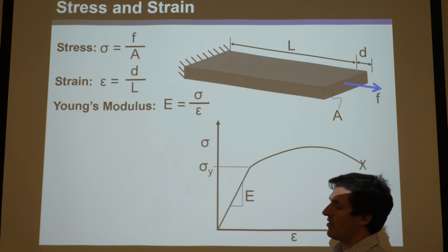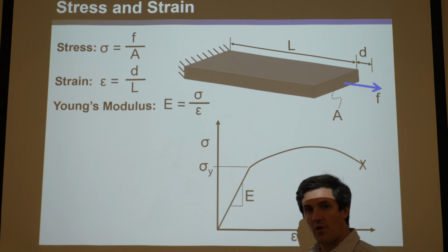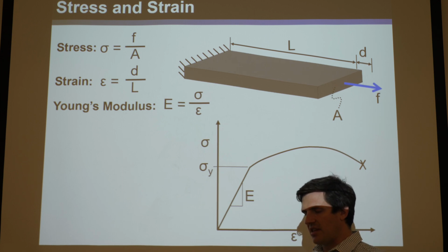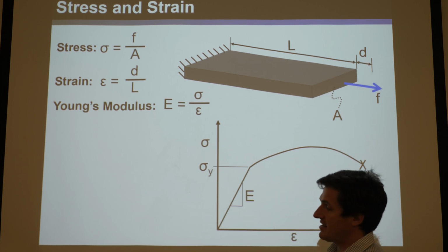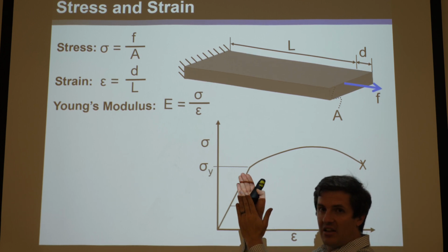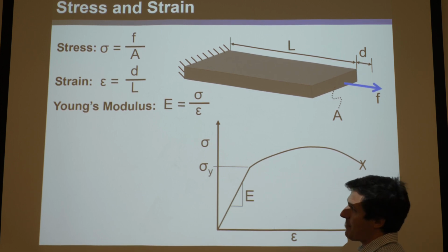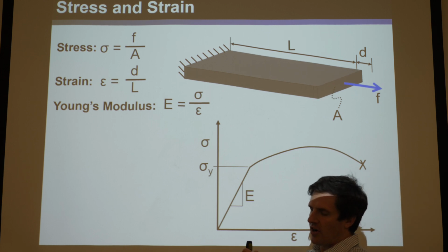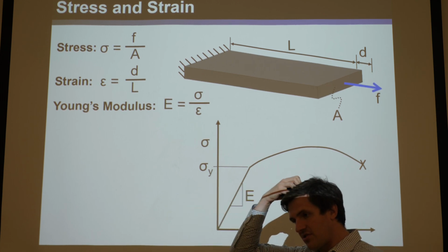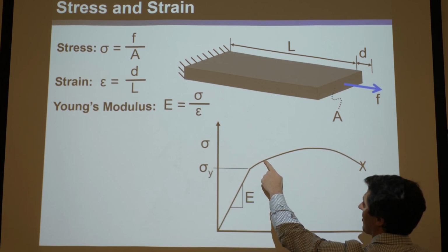And that's why, if you get a hanger and bend it back and forth a lot, plastically deforming, it'll get very, very hot, and you can actually burn yourself. So heat is released, and it's considered internal friction. And these atoms, you can see them dislocating along certain slip planes as they break and reform, and that's what's happening. That occurrence is a permanent deformation. Of course, once you break and dislocate the atoms, they don't just suddenly snap back. They remain permanently deformed. So what happens is plasticity occurs.